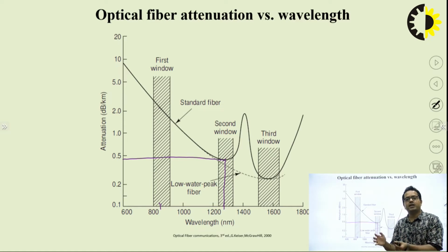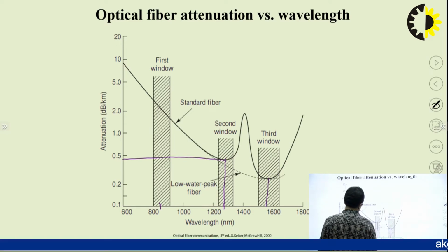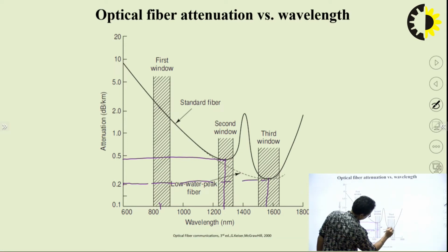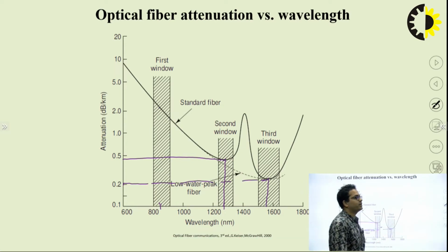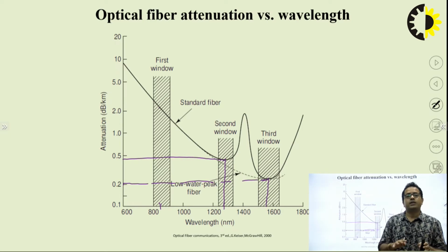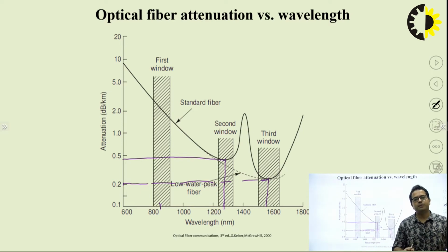It is not easy to design the optical amplifiers or various other optical devices at this 1300 nanometer wavelength. So that's why we are concentrating on 1550 nanometer wavelength, in which we can easily find that the attenuation will be around 0.2 dB per kilometer, and the various researchers, with the modification in the techniques that they are using for purifying the fibers, have reduced the attenuation from 0.2 dB to 0.12 dB per kilometer.